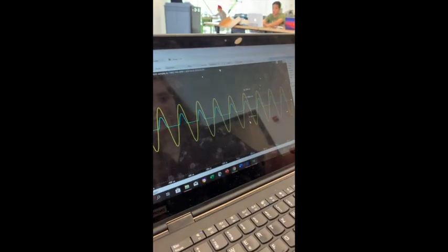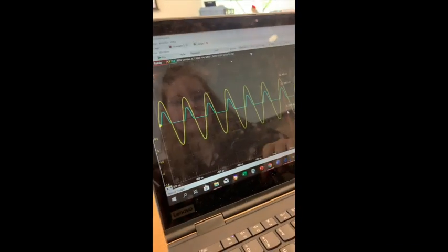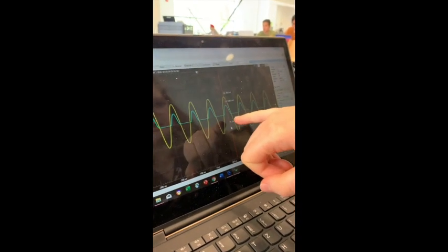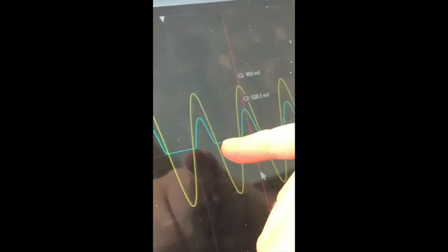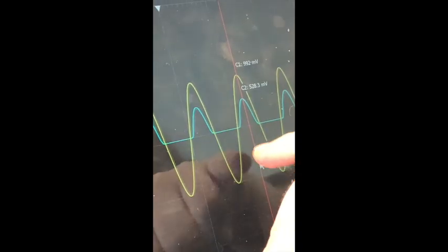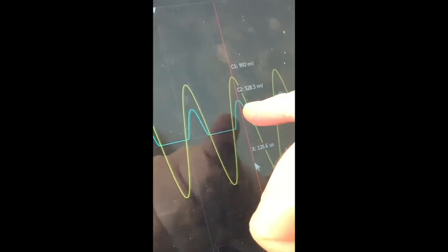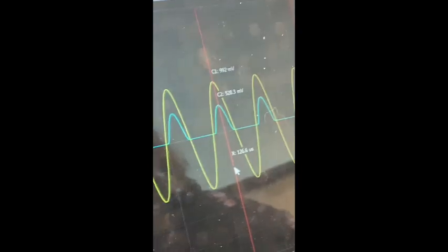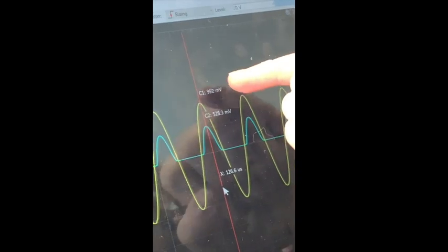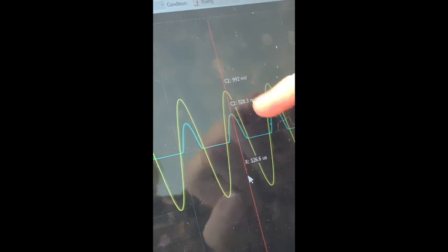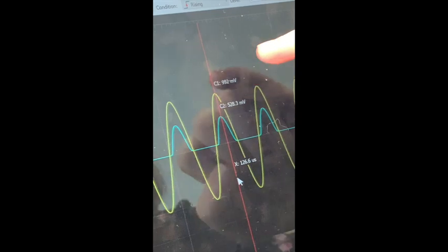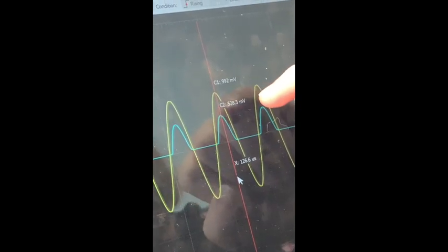So our waveform when the input voltage is 2 volts peak to peak, and we can see this without the capacitor, sorry. And again we see that when the input voltage is negative, there's no voltage across the resistor, as we saw previously. And it's easier to see the offset, which is around 500 millivolts. If we subtract 528 millivolts from 992 millivolts, it's almost 550 millivolts of difference.